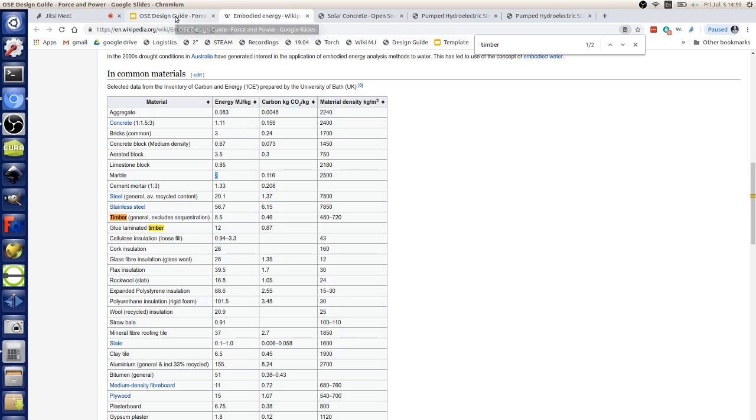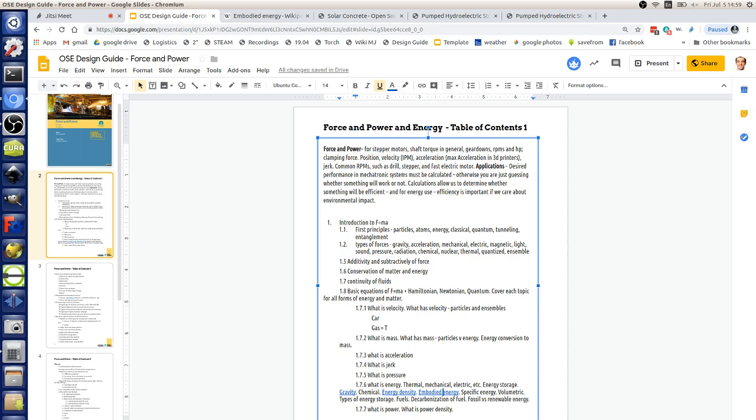So anyway, moving on, let's almost start wrapping up here. Specific energy is energy per mass. So when we talk about energy density, we're talking about per kilogram. You have to be careful whether you're talking about per mole, which is per number of molecules, per volume, or volumetric energy density, or specific, which is per weight. Hydrogen at room temperature and pressure would be a huge volume, because it's the lightest gas. A kilogram of that will take a huge volume, but it will have 3 times as much energy as a kilogram of fuel. So you probably have to compress it to make it practical to drive a car with it.